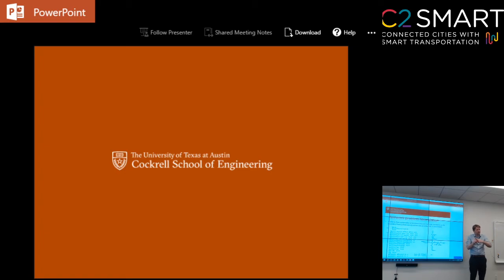This is a macroscopic model, so the only prediction of the model is that you have some densities and the speed is a function of density directly. You don't have microscopic behavior taken into account here. So the only way to incorporate, for example, some loss of capacity because of waving, is to physically change the capacity parameters of the junction. You have no other way to take that into account. It's not a microscopic model that describes that.